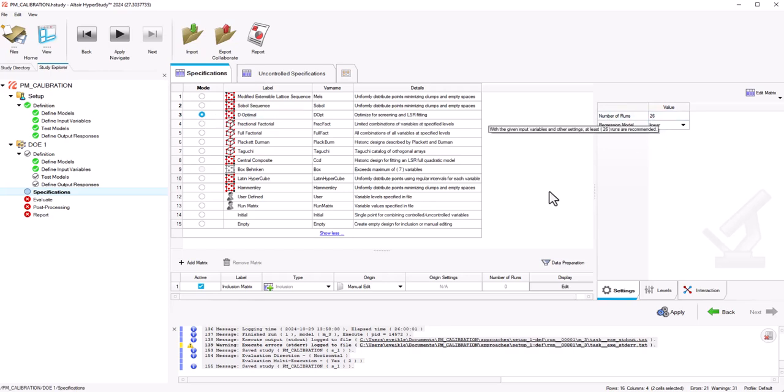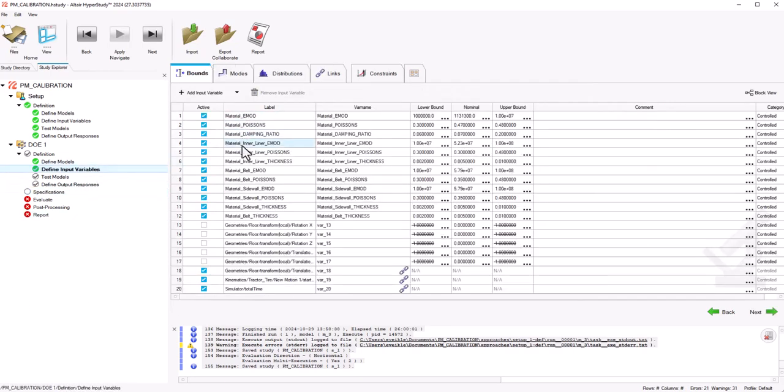So what this is going to do, the objective here is twofold. First, we want to identify which of these input parameters has the most influence on minimizing the area between the two curves, the area between the two curves being the simulated virtual tire Z force response versus the reference data set.